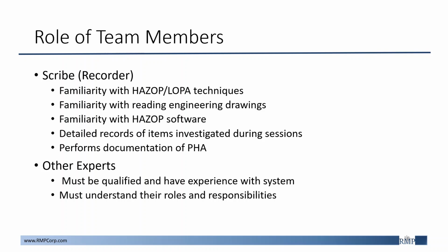The quality of the PHA is reflective of the quality of the team members, and an effective selection process can help limit the possible time in a session due to team members not being aware of their roles and responsibilities. This is why scheduling early is important for a successful HAZOP, and developing a timeline is useful to achieve this.